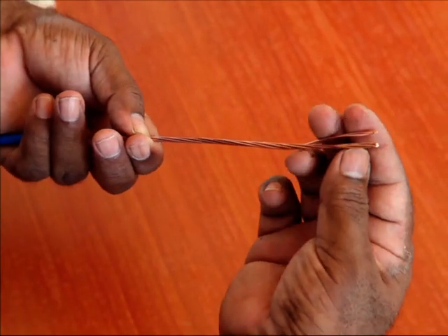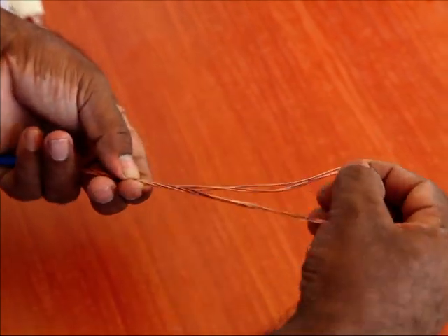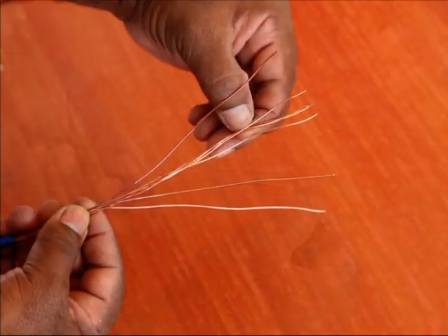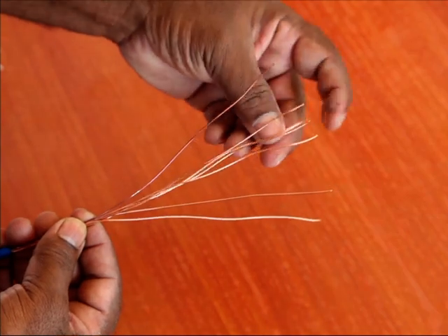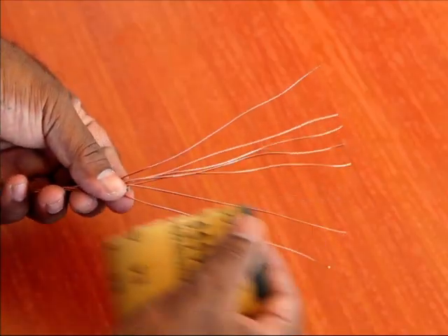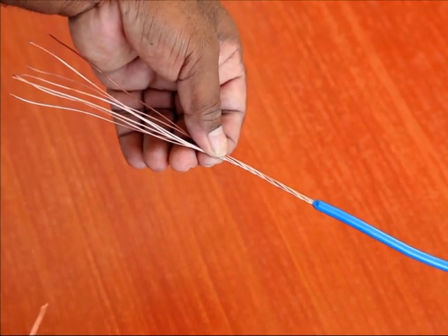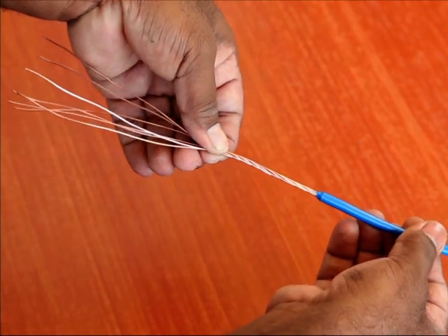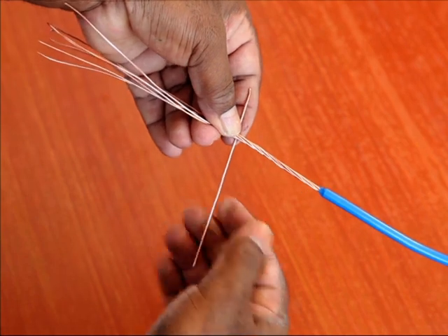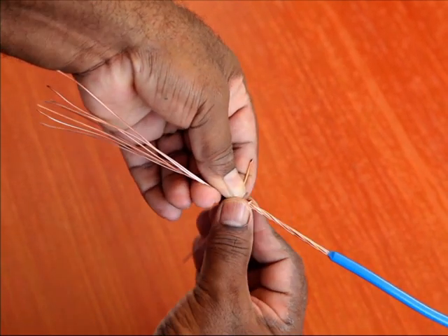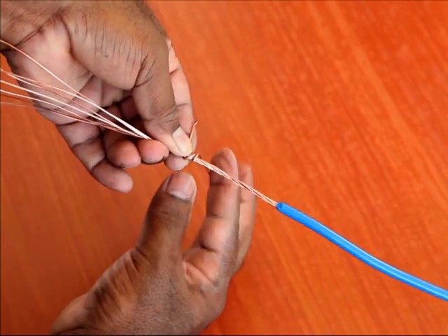Open the strands of the tap cable and clean them. Use smooth 00 sandpaper if necessary. 6. Retwist the strands in the original direction. Make a binding on the twisted part of the tap cable, up to 50 mm from the insulation.